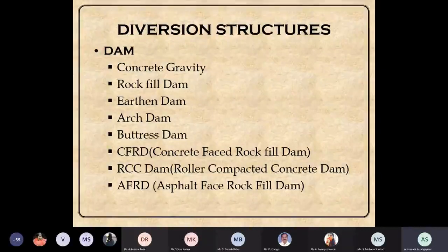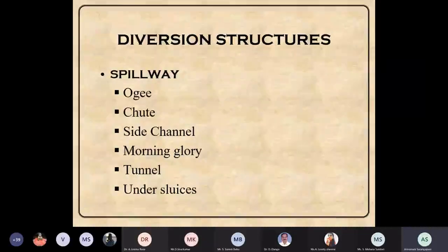And in the dam we will have a spillway. A spillway is nothing but a means to spill the water from the dam to the downstream. When we are using the water for hydropower, we will have a tunnel and intake separately, and the excess water will be spilled out from the dam during flood time, or if necessary, from upstream to downstream.